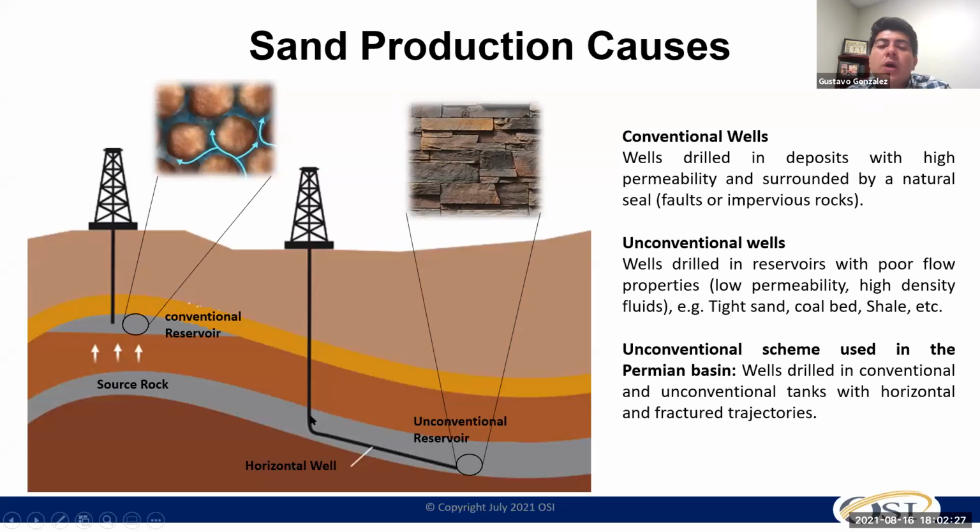On an unconventional well, we go with a different approach. We try to keep our wells vertical for the first 8,000, 5,000, or 10,000 feet, case by case, and then we go 1 mile or 2 miles on the horizontal section, so we're able to have better communication and keep all our production area right in the middle of that reservoir. So hopefully we get a better inflow, we're able to lift more fluid, and maybe use a different method to approach that.